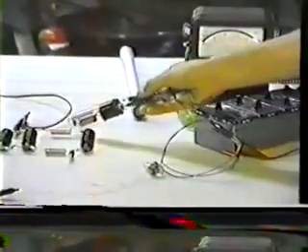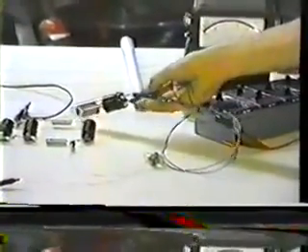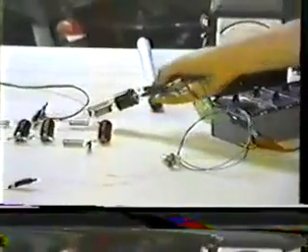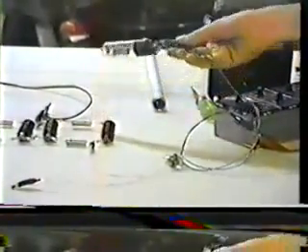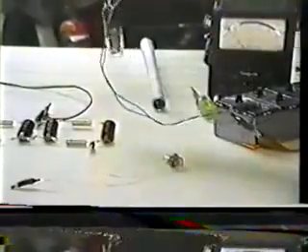And we can see that the phototube responds quite readily to the longitudinal dielectric induction existing at the end of this, primarily due to the presence of ionized gas. Get behind here so you can see the meter. See, it just jumps right up. Even though the illumination by the gas in there is barely visible, and of course I have a big 750 watt bulb hanging right up there on the ceiling, and that produces hardly any output at all. Now we'll go back to the board and do a little brief description of what multipactor action is all about.